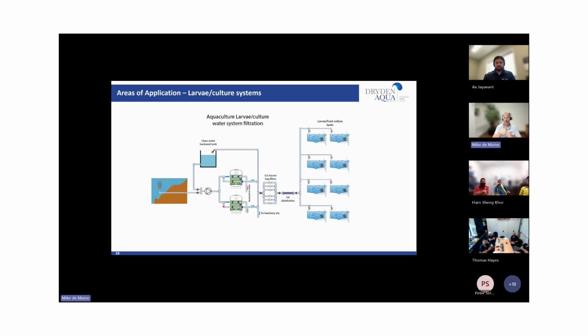Okay, so if we look at how AFM works, because AFM uses a lot of adhesion for pulling out the fines, the first stage of AFM generally deals with all of the large particles and some of the fines. The second stage of AFM, running at a slower velocity, is really focusing on removing fine particles even into the submicron range. You will, on those second stage filters, if you do it in this way, just so that you're aware, you will never see a pressure increase on your second stage filters, because all the larger particles have already been dealt with in your first filtration.